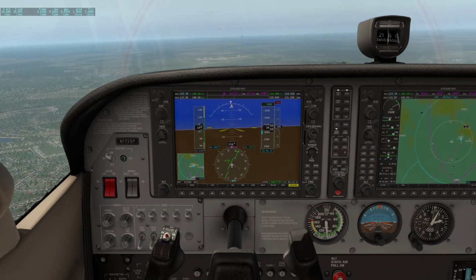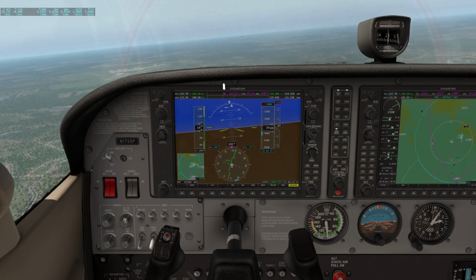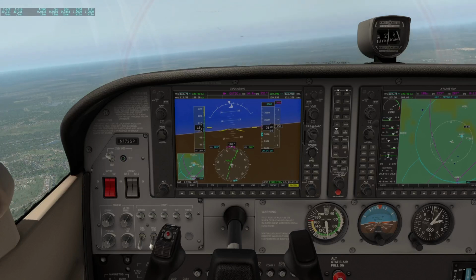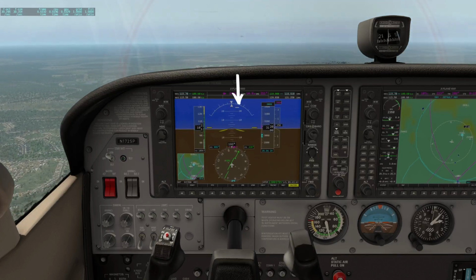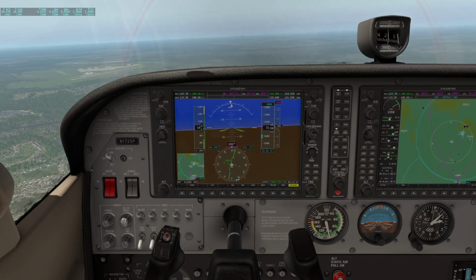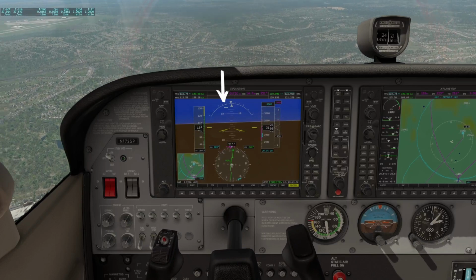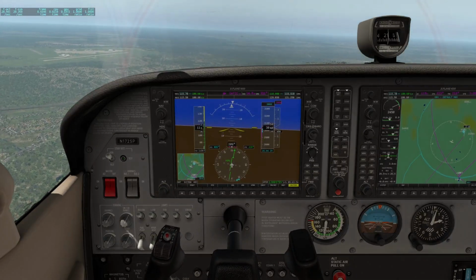So as we're flying, we can demonstrate if you give it too much rudder, the brick slides out from under the arrow. So then you need to step on the brick that's corresponding to that side of the aircraft. So right now I need to step on the right rudder to slide it back under more. Now I need to step on the left rudder to center it back up. And here it's centered again.